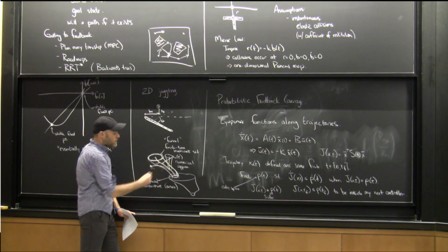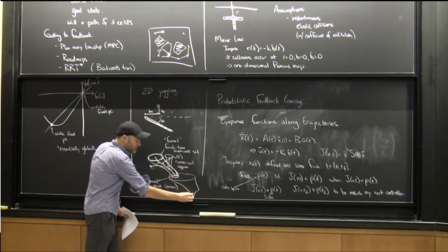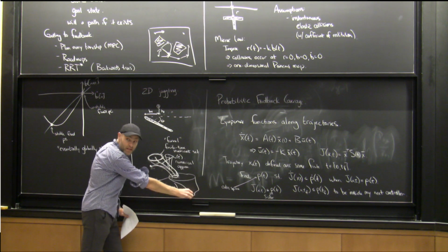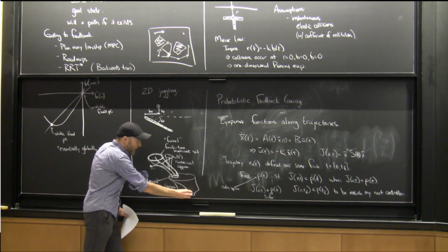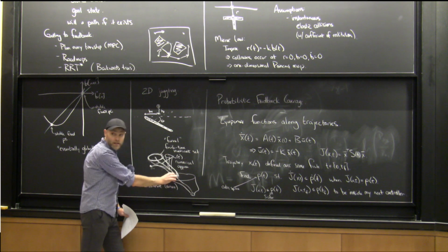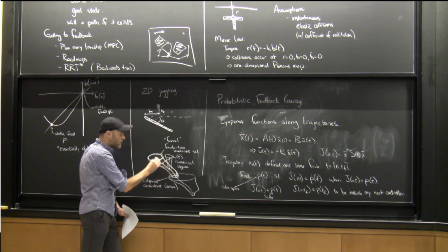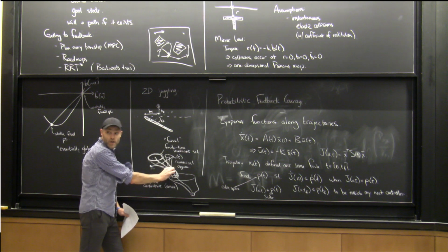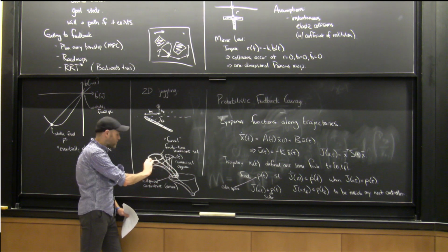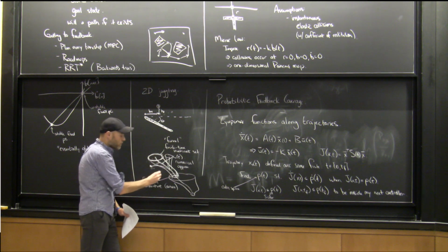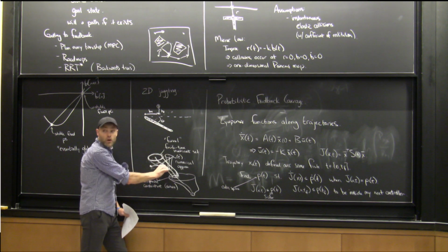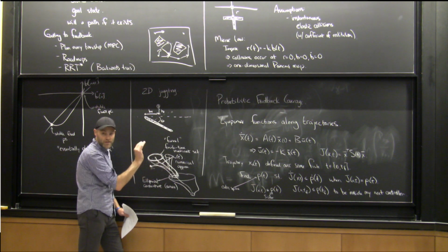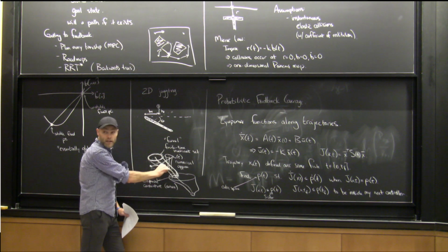Yeah. So at the goal I have the LQR solution, which is the Riccati equation. I work back here, I have a Riccati equation that's defined for the time-varying linearization along here. I have it defined everywhere here, and when I add a node to the tree, I pick up that time-varying Riccati equation and continue to integrate it backwards along the time, okay? So if I were to stop here, I don't actually know how to start my TVLQR. I don't have the Riccati equation continued. That's maybe a technical thing. You could probably get around that.